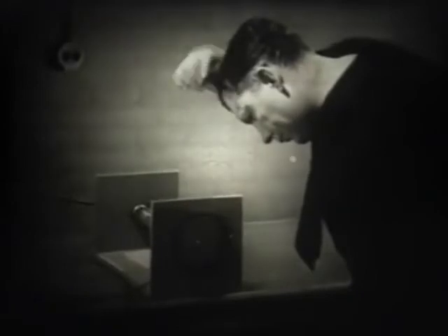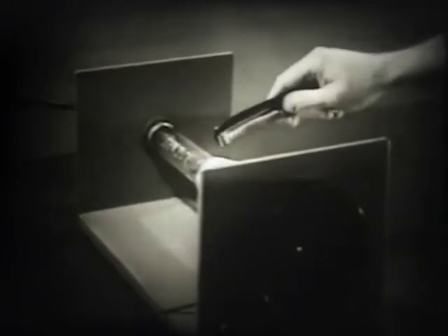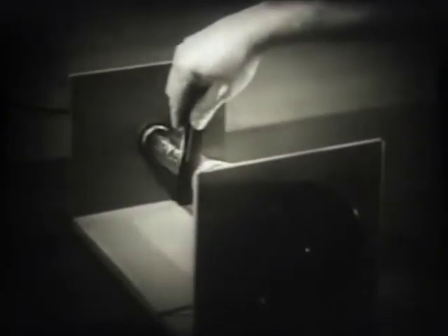For example, we can give a hard rubber comb a charge of static electricity. The negatively charged hard rubber comb will deflect the beam. As the comb is brought closer, the spot moves down, away from the comb, because like charges repel. As the comb is drawn away, the spot returns to its original position. In the same way, we can move the spot to one side of the screen or the other. Repelling the electron beam with a negatively charged medium is called electrostatic negative deflection.